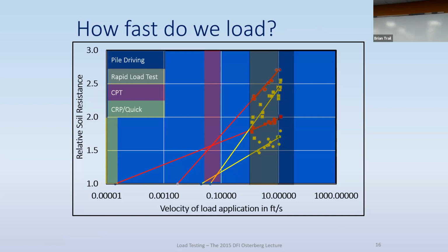But anyhow, they did some impact testing on dry axial samples and measured the forces during that impact and at certain velocities at the bottom here. And so they were doing it with typically 5 to 10 or so feet per second, which is at the lower bound of what we encountered during pile driving.